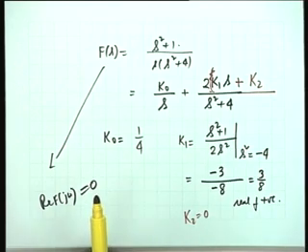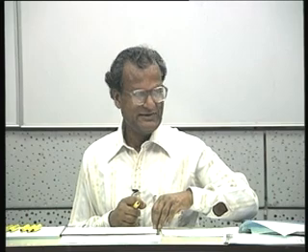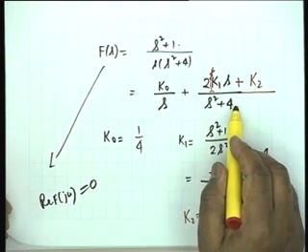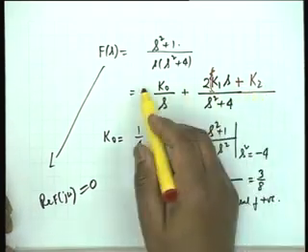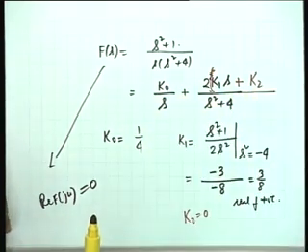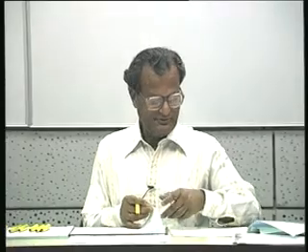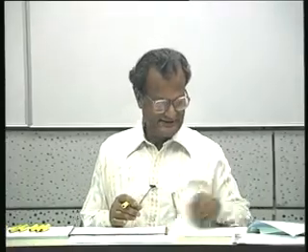Does that satisfy everybody? Do it the way you like. But what I say, it is a purely odd rational function, numerator is purely even. Now, by combining these two, if k2 is non-zero, we shall not get an even polynomial in the numerator. They are very simple common sense arguments, alright. Therefore, k2 must be equal to 0.